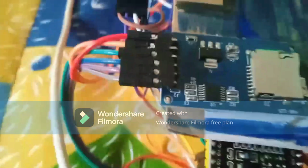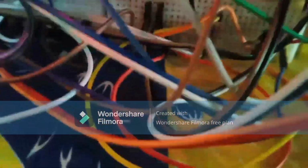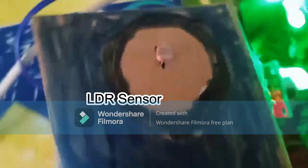And then we can see the core of our system, which is the ESP32 module, which processes the sensor data and enables the wireless communication, which sends the data to the cloud for the mobile app for remote monitoring. Then we can see the LDR, which measures the light intensity by changing its resistance based on the amount of light falling on it and allows us to monitor the light levels.